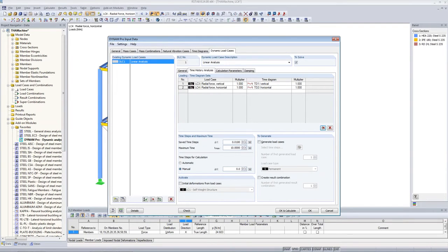And when I calculate this, I end up with this time step. It's even smaller because I have defined my save time step this way. The save time step is just for a smooth curve later on. So if you want to have a smooth graph, a time course graph, then you have to reduce the time steps here. If you do not need this, then you can increase the time steps because this saves, of course, memory and calculation time, because also the saving takes some time.